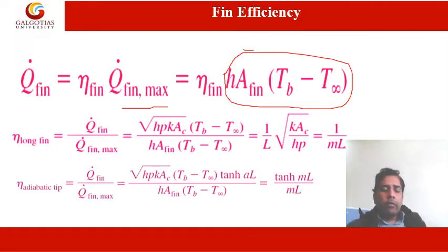If we multiply this maximum heat transfer rate from the fin with the fin efficiency, we will get the actual heat transfer. Now let us write this for each and every case.